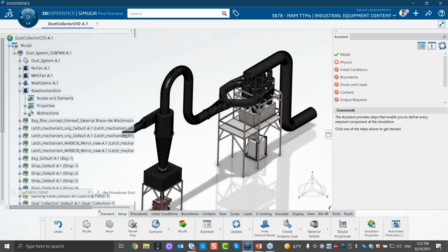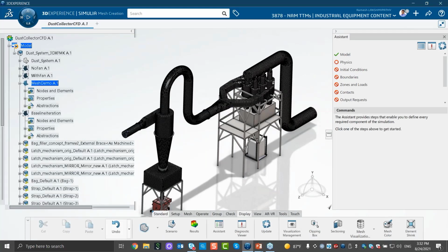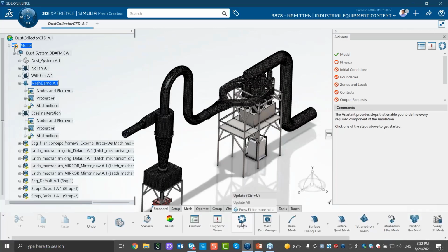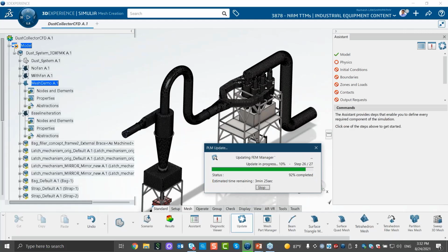This is in Fluid Dynamics Engineer. There are several options to help you mesh the geometry. Well, for fluid regions, typically the hex dominant mesh is used. But what I want to show and illustrate here is, for example, how easy it is to create boundary layers.